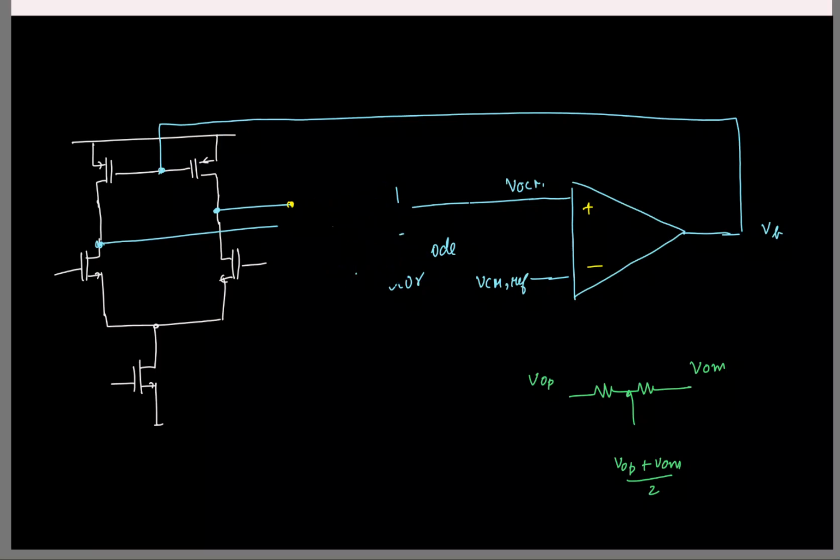So now this big block is basically two resistors, and I'll connect them like this. Okay. So let's say I call this RCM because we are sensing the common mode, and then we'll do it. Okay, and the simplest common mode feedback loop you can have is this.